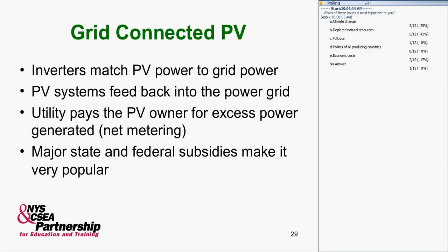Basically, what we do now is we generate power on a rooftop. If we need the power, we use it. If we don't need it, it gets converted to match the power utility's electricity, same phase, same frequency, same voltage, and we pump it back in. Our meter runs backwards. Electricity goes from your roof right to the telephone pole and powers one of your neighbors or somebody else. The meter spins backwards, your bill goes down. When you use power at night, your meter spins forward, your bill goes back up. We call it net metering.